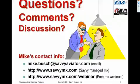I think this is a training issue, because we have two magnetos for a reason, but the redundancy involved in having two magnetos doesn't help much if the pilot doesn't have the presence of mind to turn off a malfunctioning magneto and run on the one that's working okay. So that's a slight departure from what the question was, but I just wanted to mention it.